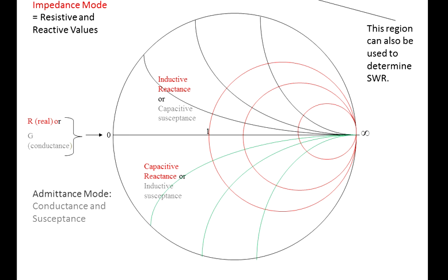So there's a couple more reactive arcs. This is by no means perfect scale, but the methodology is correct. Now, take note of the arcs intercepting some of the circles. Where those 2 points meet, you will have an impedance value. For example, where the red line from 1, or the normalized value, intersects the first reactive component, where those two meet, you will have an impedance value, what's called a normalized impedance value. Once again, part 2 will give you a better insight into that.